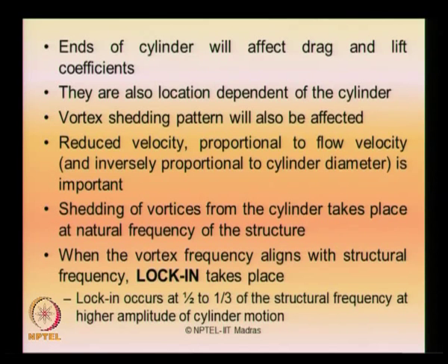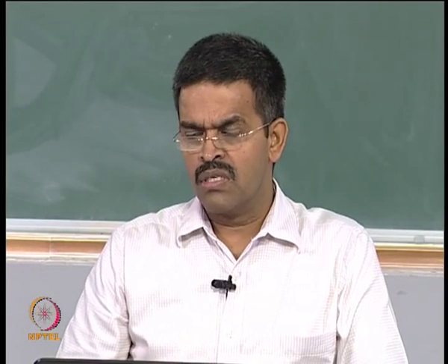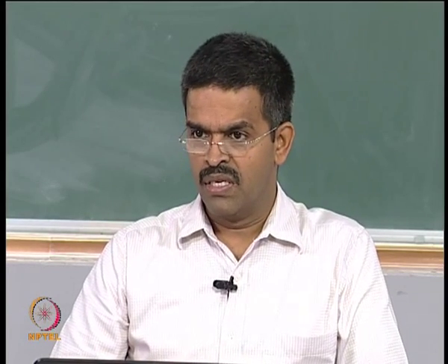Now when the vortex frequency gets aligned with the structural frequency, something called lock-in takes place. What is lock-in? Lock-in actually occurs at half to 1/3 of the structural frequency, and the amplitude is very high. So it starts vibrating at about 50% to 33% of the structural frequency.